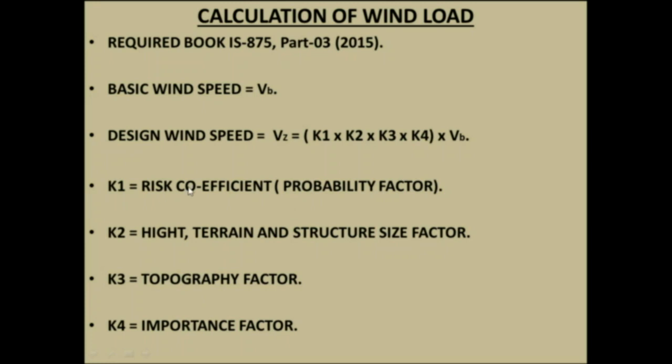K1 is the risk coefficient or probability factor. K2 is the height, terrain and structure size factor. K3 is the topography factor. K4 is the importance factor.